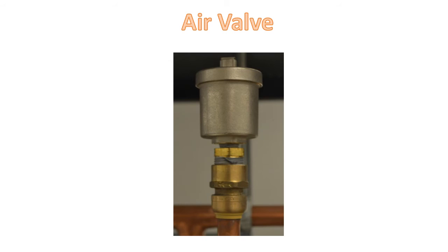All hydronic systems must have a means to eliminate air from the system. Air causes irritating system noises, as well as interrupting proper heat transfer to and from the circulating fluids. Besides, the oxygen dissolves in water and causes corrosion.